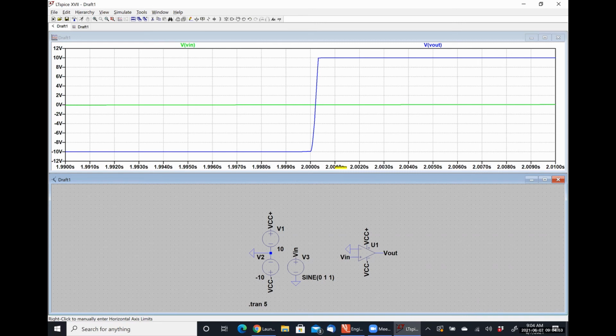To be entirely honest, we're probably going to finish 30 minutes early tomorrow, just because the different ways that we can use a ludicrously high gain are actually pretty limited. Negative feedback op amps have much more use because we can set a gain to a specific value and do lots of things with it. With these guys, we're just stuck with whatever gain the op amp has. And typically it's really, really large, which means we have a really, really small linear range, which means the question is how can we get as creative as possible about the ability to generate a square wave and use it for something.